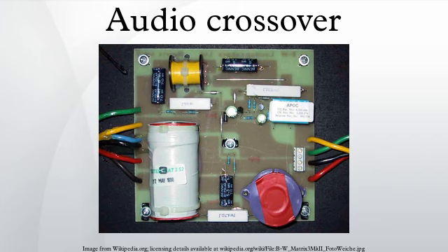Recently, a number of manufacturers have begun using what is often called N.5-way crossover techniques for stereo loudspeaker crossovers. This usually indicates the addition of a second woofer that plays the same bass range as the main woofer but rolls off far before the main woofer does. Remark: filter sections mentioned here are not to be confused with the individual two-pole filter sections that a higher-order filter consists of.